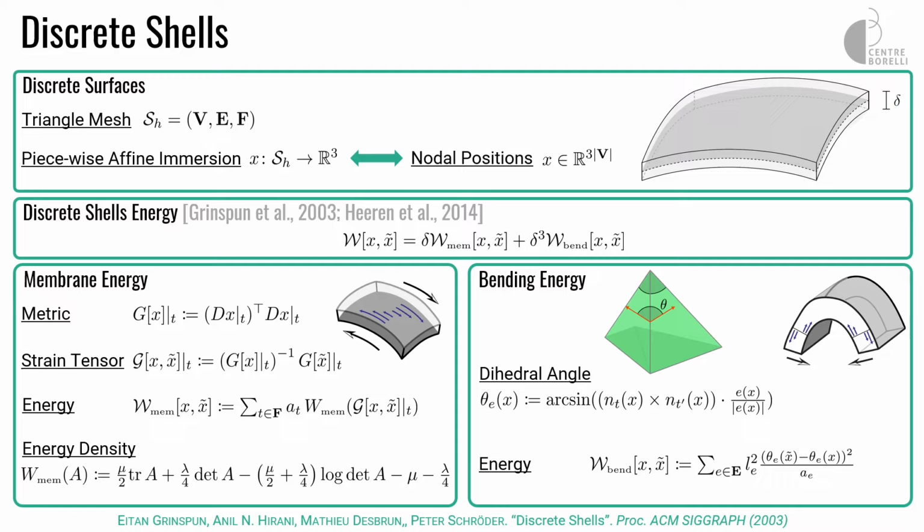Yes, with respect to the reference shape. And so typically, you could also say, okay, this is the energy of the difference between these two with respect to some reference configuration, which is given by this X itself, and then you would integrate over this reference configuration. Yeah, well, maybe that's a good thing to say. It's a bit non-standard for elasticity, but it's just a benefit or side effect of this discretization.